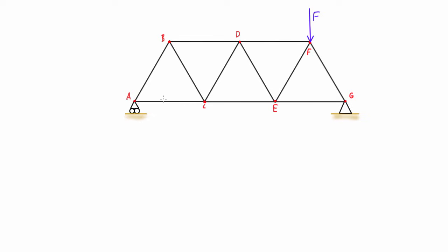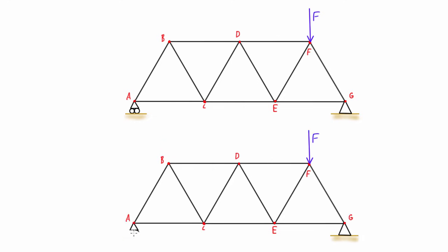So the first thing that we need to do is treat our entire truss as just a single structure, and we want to draw the free body diagram for the whole truss. So it'll look something just like this, where we have our one applied force and then we have our two reactions. There's no horizontal applied forces here, so we don't even have to worry about putting a horizontal force here, because there's only one vertical force acting down. So both of these supports are just going to be acting opposite to prevent that sort of translation of the whole thing down through the page.